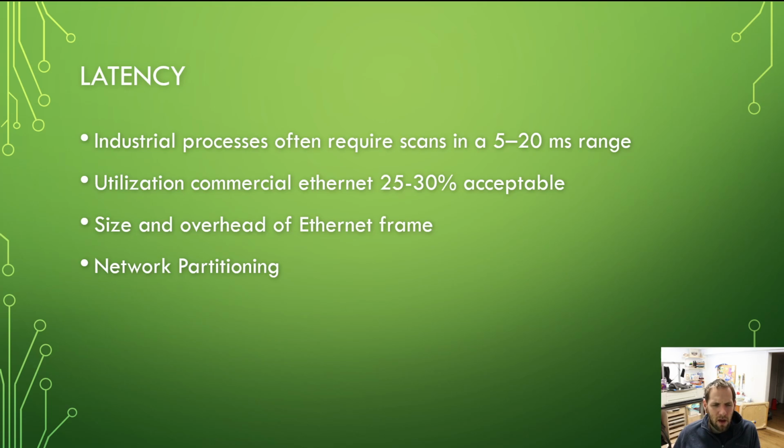So on a 100 base T Ethernet, a heavily loaded 100 station network could range anywhere from 10 to 100 milliseconds. All right, which again for industrial applications is probably not going to be acceptable. If you're at 10 milliseconds, hey, that's fine. 100 milliseconds is probably going to be too long. This again is acceptable for offices, for home use. 100 milliseconds, no issues.